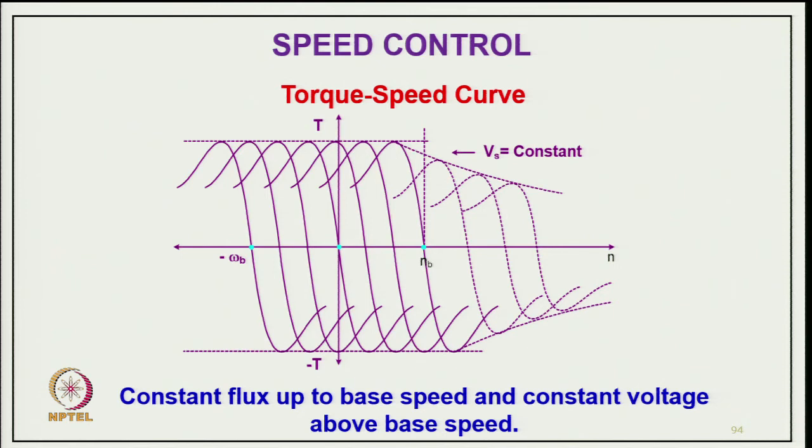And of course these can be in 4 quadrant operation, because in many cases you need a reversible drive, like traction. You have reasonable regeneration even in metro and traction, and even in electric vehicles. So, a lot of applications have active loads, and we can get regeneration by reducing the frequency of the stator winding. It can work as an induction generator, by varying the frequency smoothly so that it develops the regulated torque with the regulated current, but we always operate the motor in the stable region.